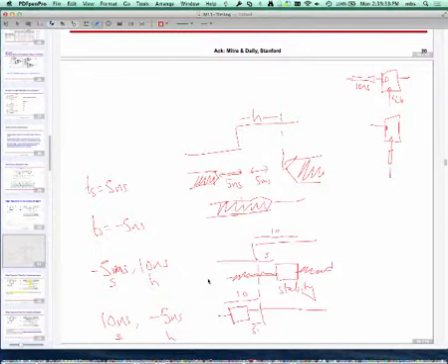So you'll ask questions like, will my chip work correctly at 1 gigahertz? Will it work correctly at 2 gigahertz? You're trying to find the right clock speed. And of course, real life is even more complex because delays of circuits change because of temperature. They change because of aging. A circuit, as it gets used more and more, slows down.